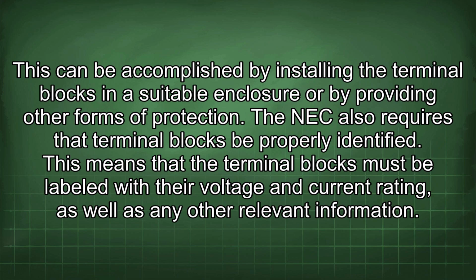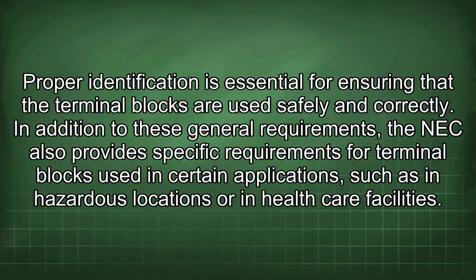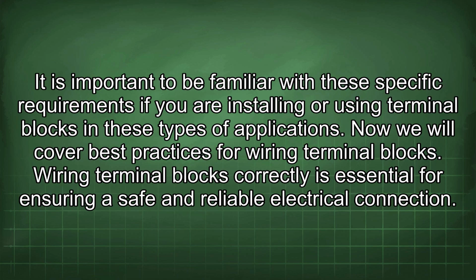The NEC also requires that terminal blocks be properly identified. This means that the terminal blocks must be labeled with their voltage and current rating, as well as any other relevant information. Proper identification is essential for ensuring that the terminal blocks are used safely and correctly. In addition to these general requirements, the NEC also provides specific requirements for terminal blocks used in certain applications, such as in hazardous locations or in healthcare facilities. It is important to be familiar with these specific requirements if you are installing or using terminal blocks in these types of applications.